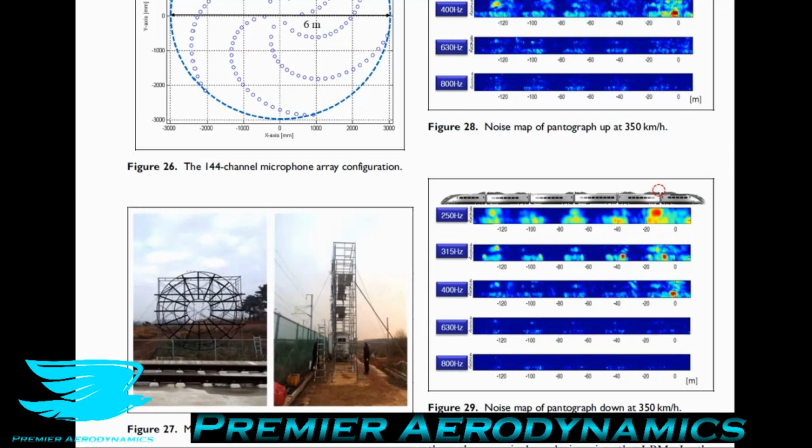But there's something called a synergistic effect or a secondary effect, or even tertiary when you couple it with other things. This is when you have both of these things together, and they have not only their own noise propagation, but noise being produced because of the interaction. One very simple way to look at this is, let's say you have two cylinders, one upstream and one downstream. If you just have one upstream and get rid of the one downstream, and you measure the von Karman street and the noise coming from that, you'll get a certain value. Then you get rid of the upstream one and just put the downstream one in, and you do the same thing. So you're going to get two different noise spectra for these things.